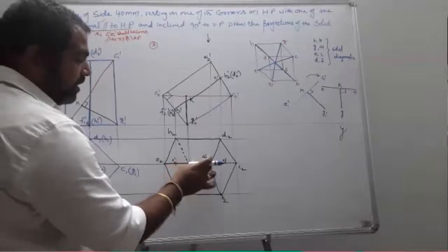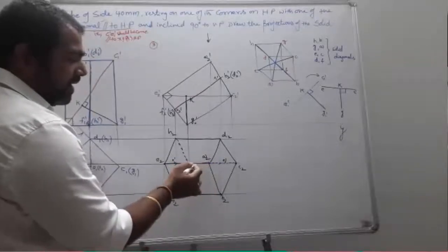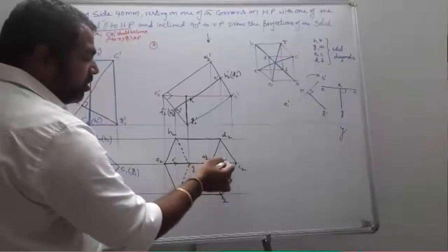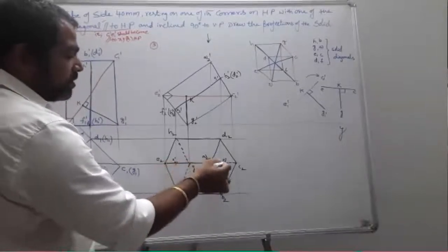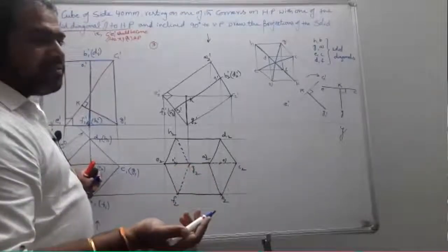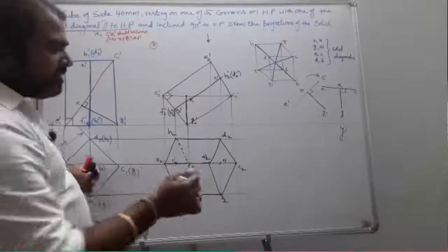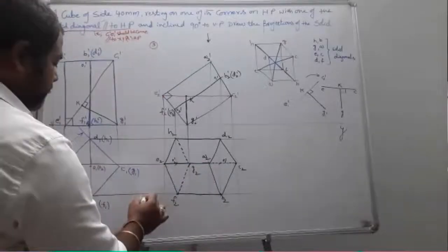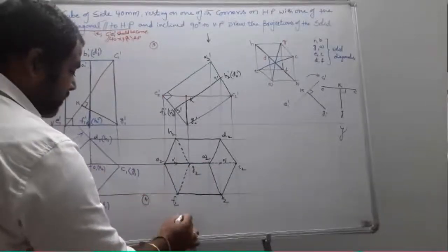So the GA dotted line is hidden by the EA solid line, and the remaining portion is going to be dotted line. So here O2 dash O1 dash is there, but I am not supposed to represent the axis. Why? Because least preference is given to the axis, but it exists, it is hidden. So now this becomes your fourth step, and this is stage 2.